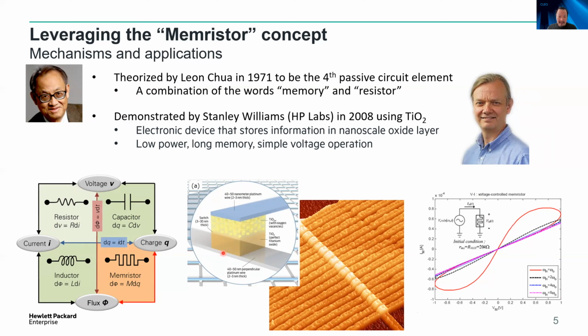In this particular device, you see there's a 40 nanometer cube of titanium dioxide consisting of 2 layers. The lower layer has a perfect 2-to-1 oxygen to titanium ratio, making it an insulator. The upper layer is missing 0.5% of oxygen, which makes it more conductive. If we apply positive voltage on this blue electrode, the positive oxygen vacancies are repelled down into the insulating titanium dioxide layer below, and that increases the conductivity of the entire switch.